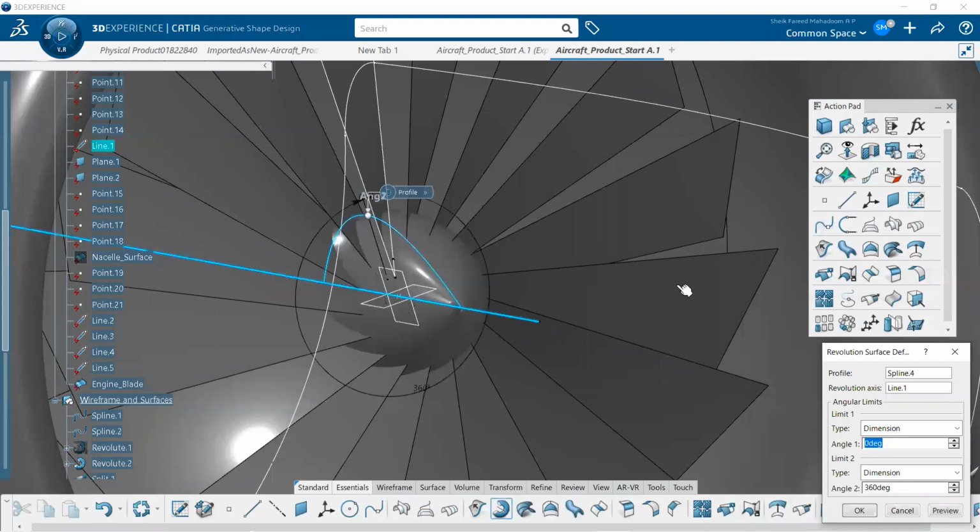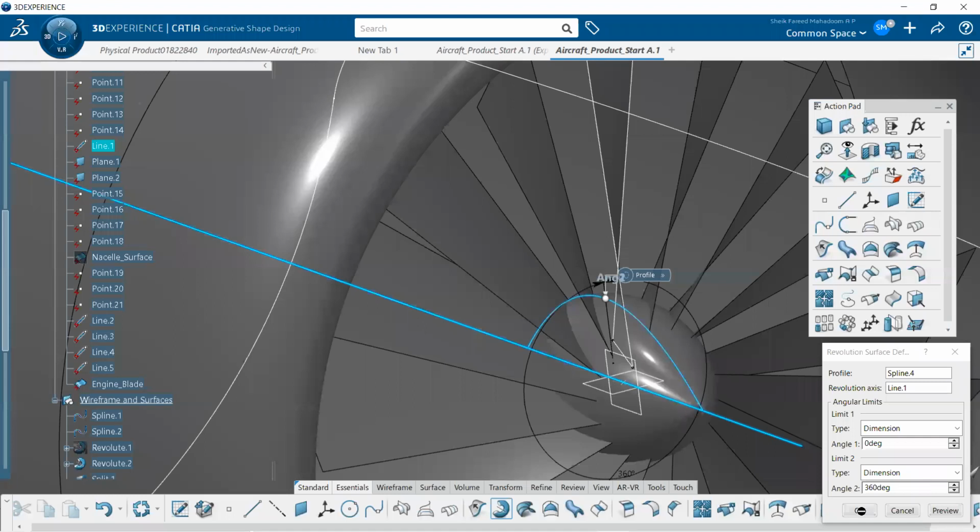Then click OK on it. Right now the plates are inside, and there will be some excess elements, so I need to split the excess elements. Just click on the split option, then select the plates, and then select the revolved surface that we created. Then click OK. Keep the sub elements. Click OK. That's it, and it's over.